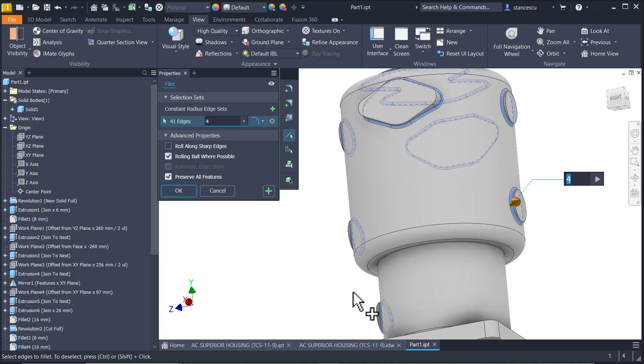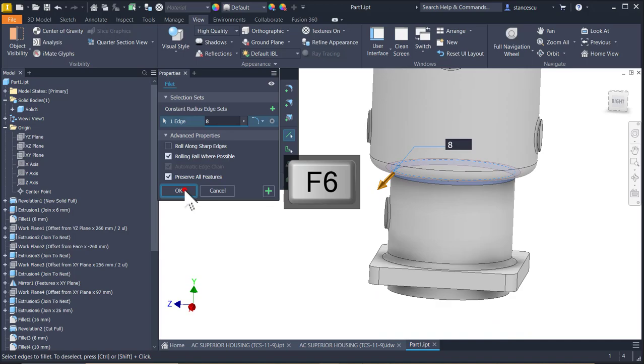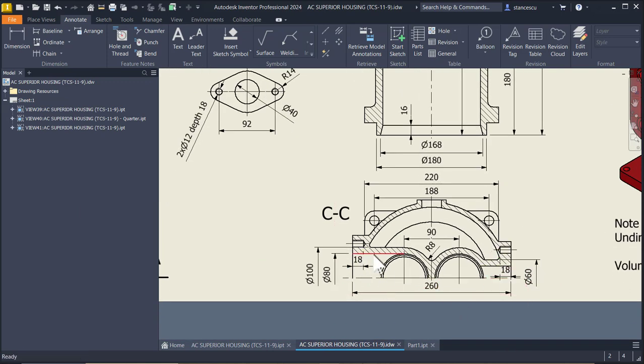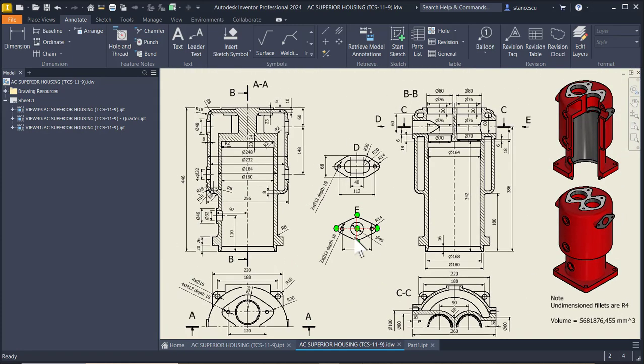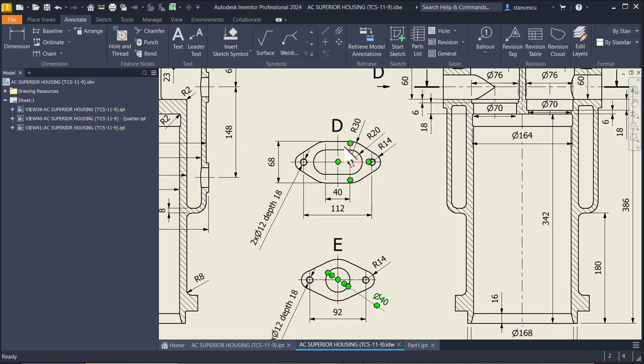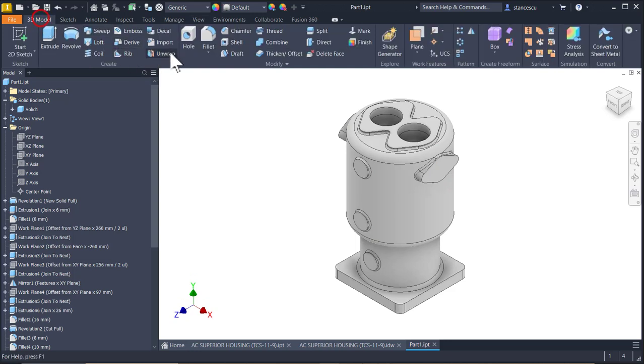This is 8 for this. Okay, now we see here a hole of 40 is this one and 80 the other one. Dimensions are here, 40 and 80 is from this point to this point. We'll create this slot with radius 20, distance of 40. Good. The depth is also 85 to be finished inside this. This is a hole, no problem.